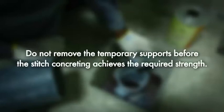Don'ts during precast erection. Excessive joggling of starter bars should be avoided. Do not remove the temporary supports before the stitch concreting achieves the required strength.